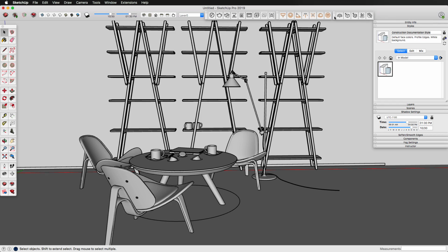This one is dealing with special V-Ray geometry, things like an infinite plane for establishing a ground surface, especially useful for exterior renderings, as well as things like V-Ray fur, which allows you to create objects with fibers on them, things like carpeting or hair on someone's head or grass on the ground, something along those lines.